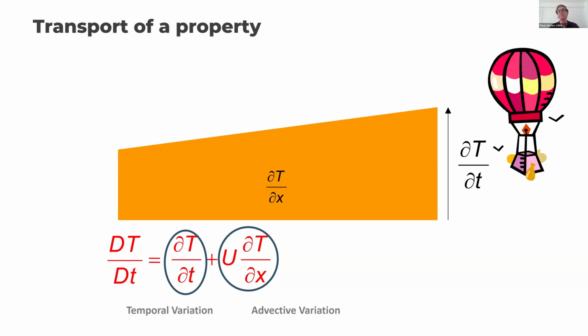Because in a fluid, we can think about a mass, a portion of fluid moving along the environment, and then we will have the Lagrangian approach, or we can think about being outside the fluid and looking at the fluid in a certain piece of space. And in that case, we have the Eulerian approach, you see? And they are absolutely equivalent.